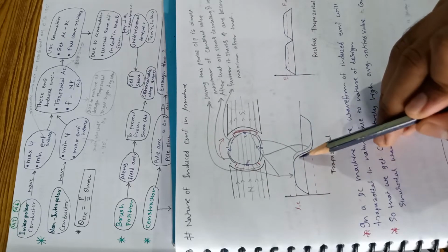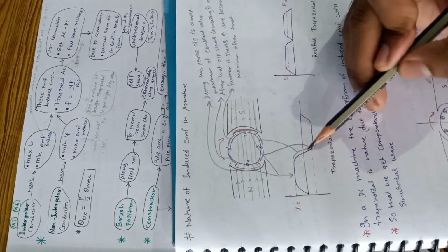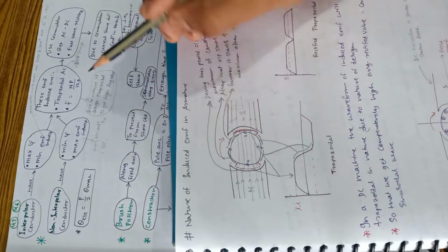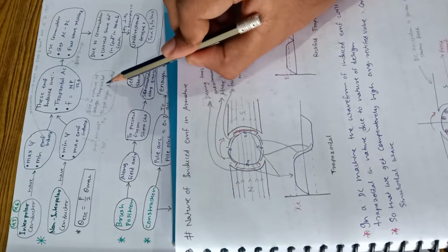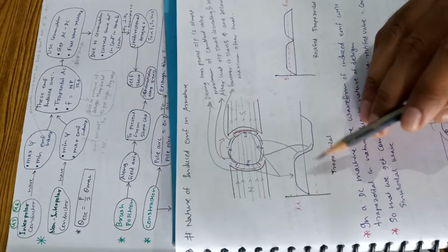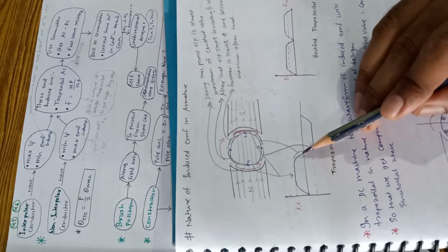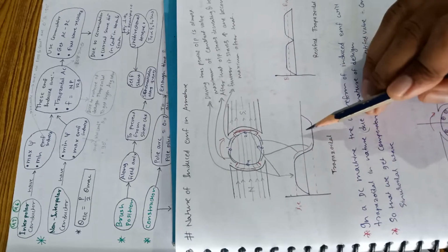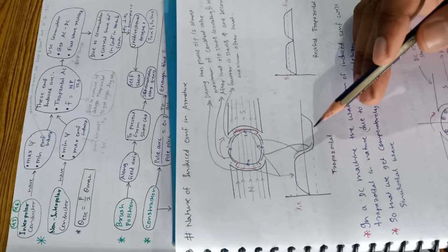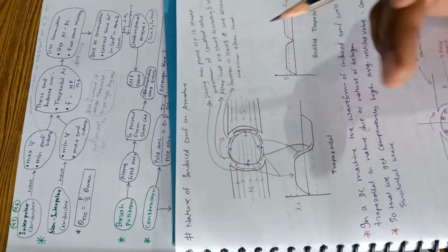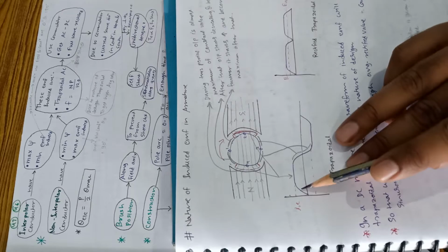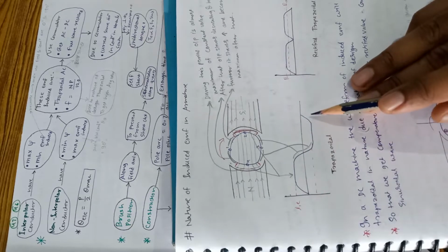See, this is trapezoidal. Due to the nature of design, it is trapezoidal. This is made trapezoidal because we can get higher average value. Higher average value means higher DC we get, and actually what we have to obtain from this DC machine is DC output only in case of generator. That's why we make it purposely trapezoidal.